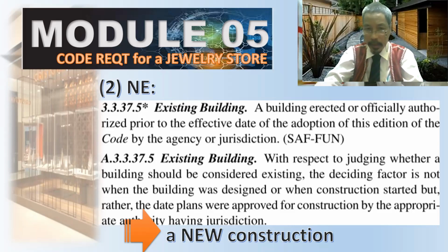That is what we mean by existing building. With respect to judging whether a building should be considered existing, the deciding factor is not when the building was designed or when construction started, but rather the date plans were approved for construction by the appropriate authority having jurisdiction. So the approval date is our date of contention.